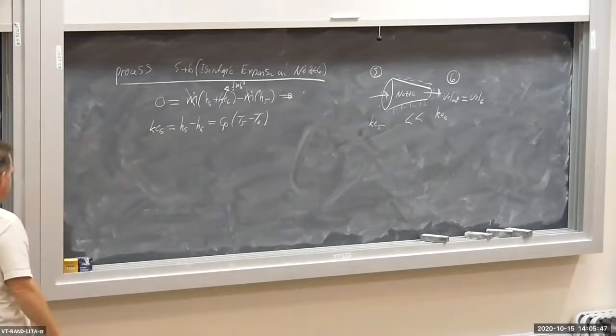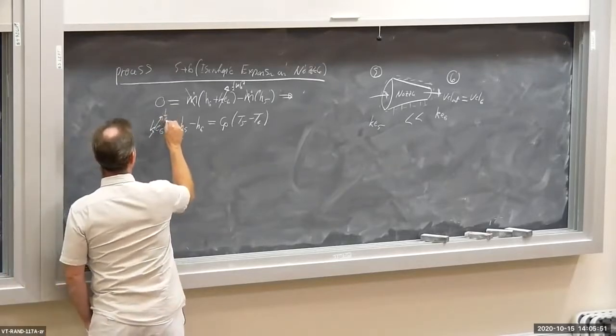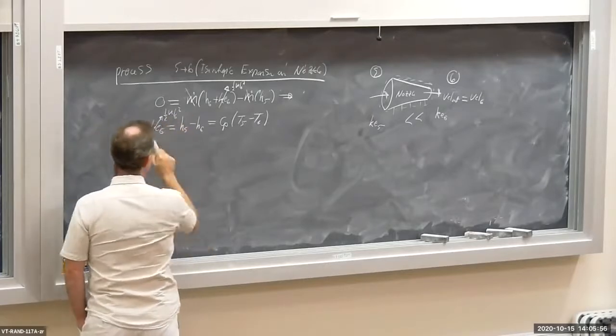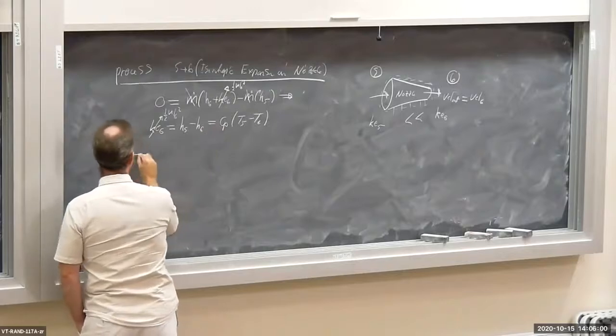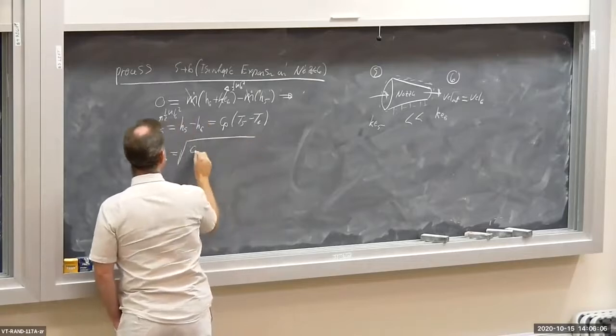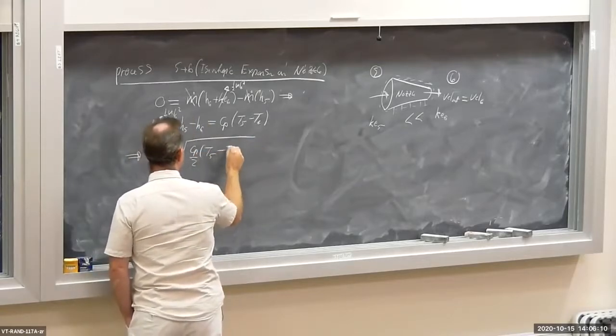Okay? Specific kinetic energy, again, is 1/2 velocity 6 squared. So let me put the 1/2 over on the other side of the equation and take the square root. So I get velocity 6 is equal to the square root of 2 CP (T5 minus T6).